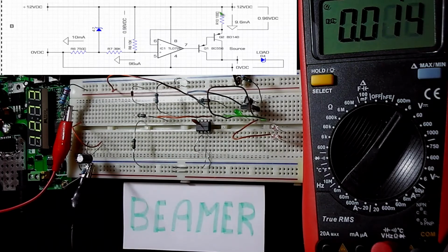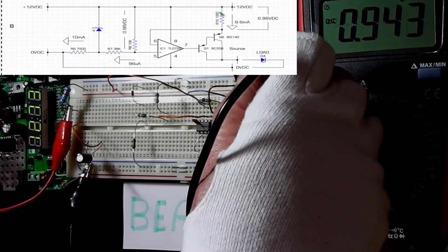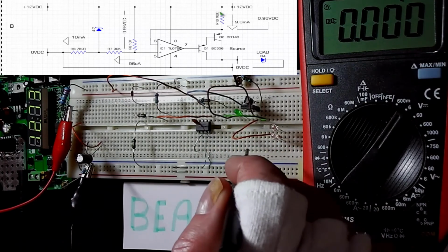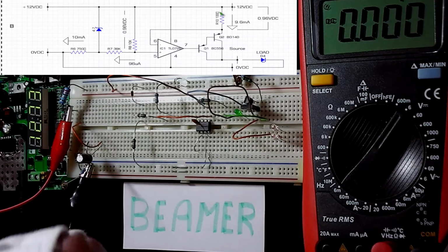Now, if I go to the emitter resistor of R10, that's the emitter of Q2, R10, the 100R, and I don't know whether you remember, but it is the range resistor position. Now, if I measure the voltage on there, which is across the 100R, I'm getting 0.943. Well, that's a little odd, a bit suspicious. I haven't got the LEDs connected to 0 volts yet, and let's just connect them up and see what happens here, and see if this corrects itself.